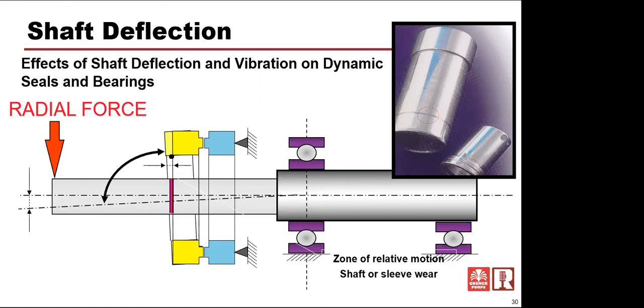Oh, absolutely. No question about it. The first thing that's going to fail is probably the mechanical seal. For obvious reasons, these faces could bounce open, or that fretting corrosion could cause leakage underneath the seal. There's certainly excess force that the pump wasn't designed to handle in this operation, and some of it can be a changing force, which is to some extent even worse.